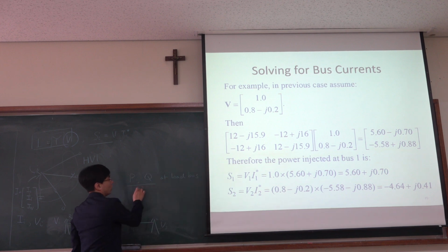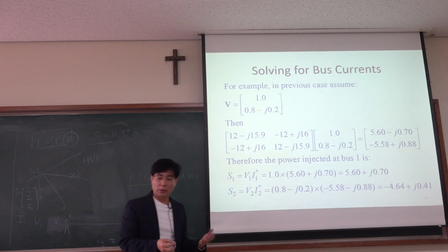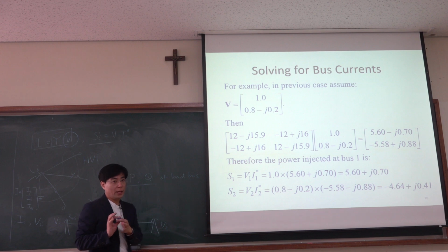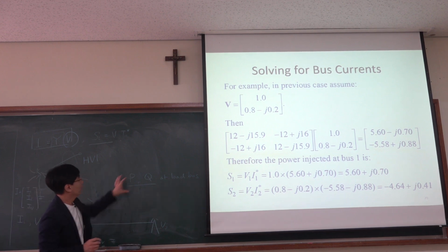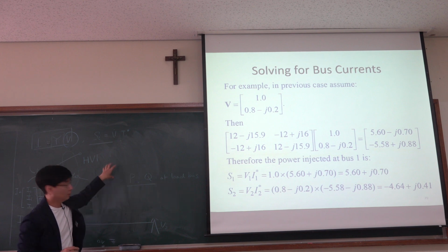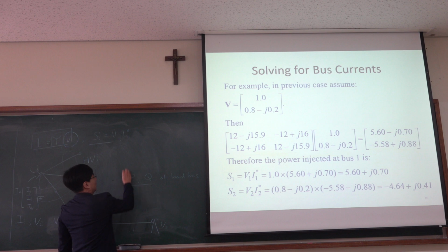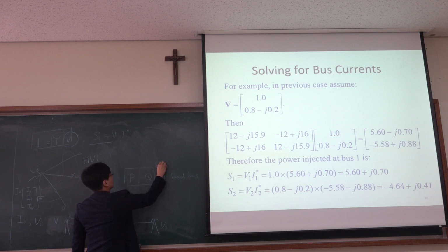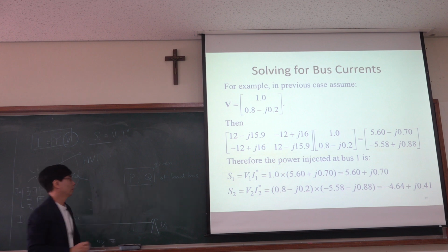And this is the requirement from the load buses. This factory, this building, this university requires this amount of active power and that amount of reactive power. And the generators need to meet this demand, active power demand and reactive power demand. Okay? So this is given, and the generator needs to satisfy this demand.